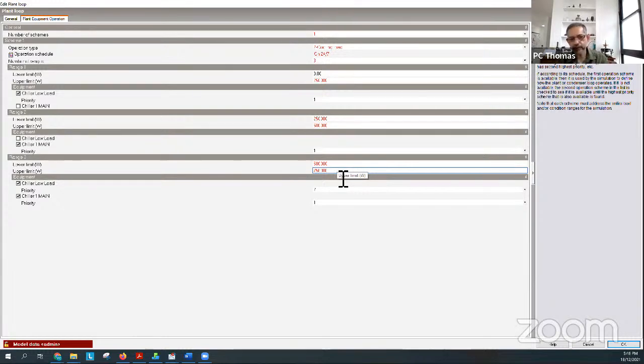So hopefully you understood that. When the building's load is less than 250 kilowatts, the low load chiller will work. When it's between 250 kilowatts and 500 kilowatts, the main chiller will work. When it exceeds 500 kilowatts, then the low load chiller will come on again. So sometimes we call this swing chiller operation. So some chillers swing in, some chillers swing out, and they keep going on.